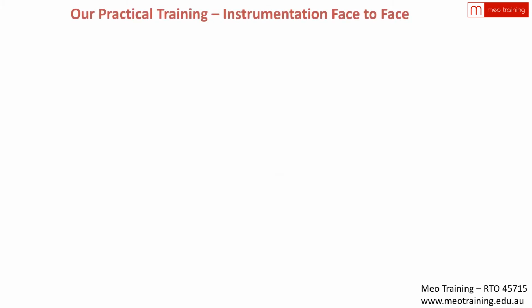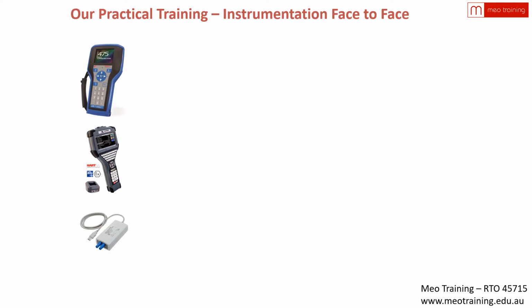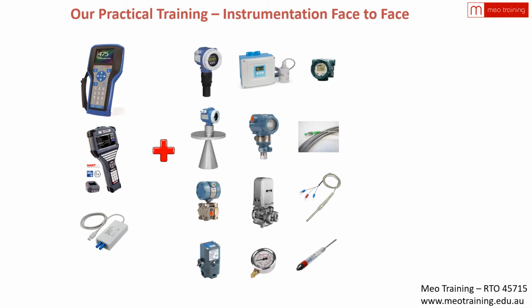When ready, you can book your practical days. We have plenty of equipment for you to train your skills. For HART communications, you'll have the opportunity to use an Emerson 475, a Meriam 5150, and also Endress+Hauser communication boxes. You'll also work with our training rig, setting up and calibrating several transmitters.